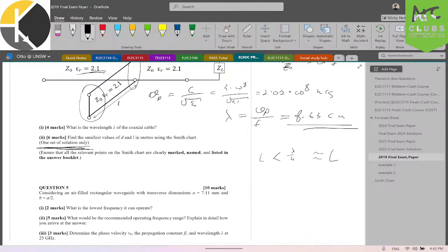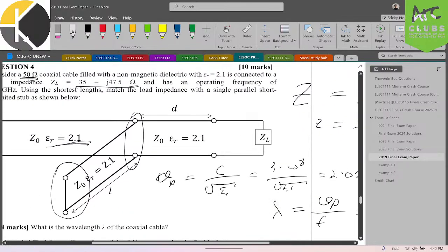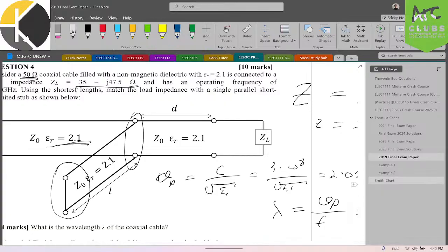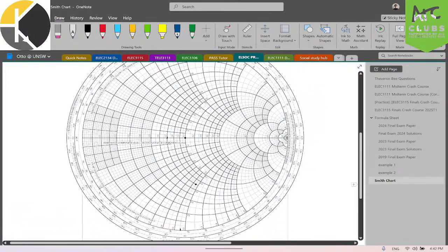It's going to be approximately an inductor. It will have inductive impedance. So you'll move upward on the Smith chart. But with the caveat that you need to reflect the Smith chart on the opposite side to have conductance, because this stub is in parallel.